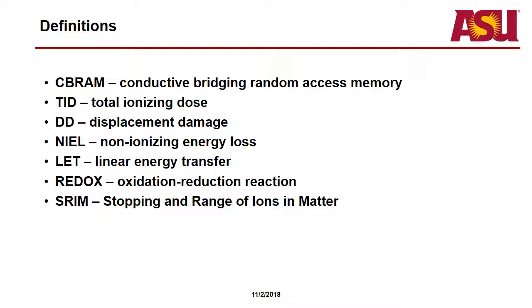One of them is CB-RAM, which is conductive bridging random access memory; TID, which is total ionizing dose; DD, which is displacement damage, and I'll also refer to it as displacement damage dose; NIEL, which is non-ionizing energy loss; LET, which is linear energy transfer; redox, which is short for oxidation and reduction reactions; and SRIM, which is a simulation software for dealing with heavy ions, and it stands for stopping and range of ions in matter.